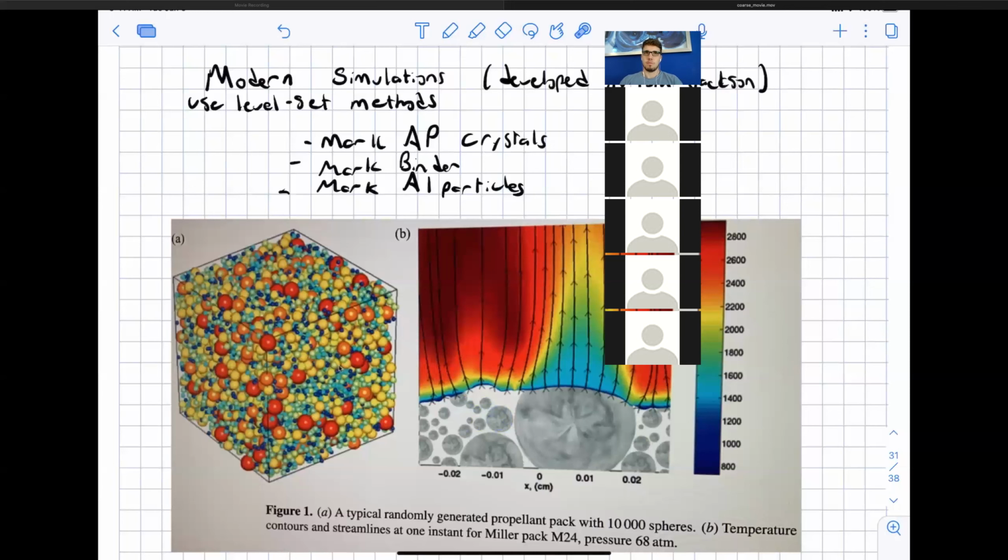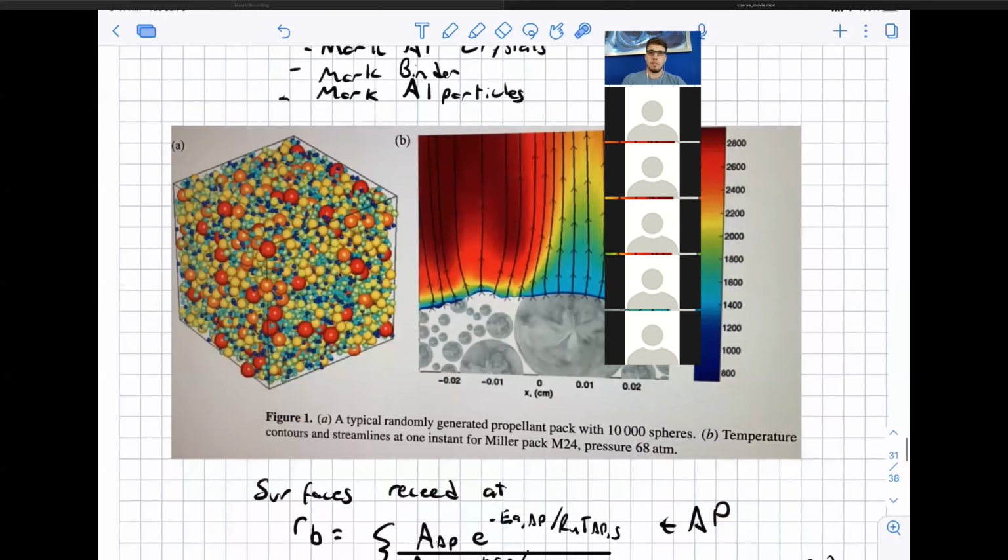They will erode it as they move by just due to friction, and also they'll stick onto the surface, and then they'll act as an abrasive when the next round moves through the barrel, and so it really affects barrel life. And so gun propellants tend to be homogeneous, and rocket propellants tend to be heterogeneous, where those effects aren't that big of an issue.